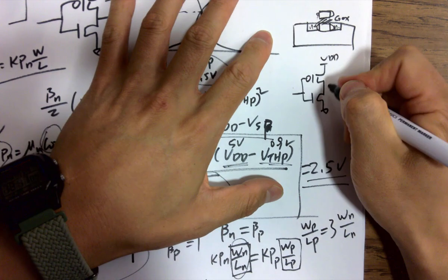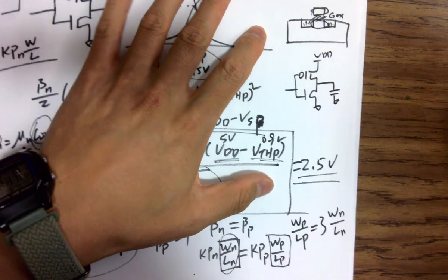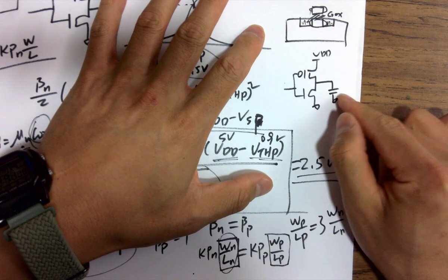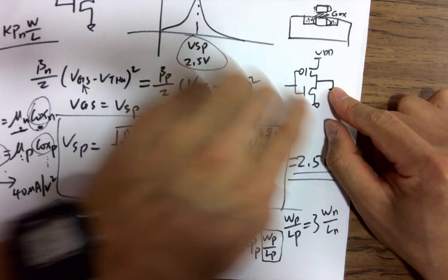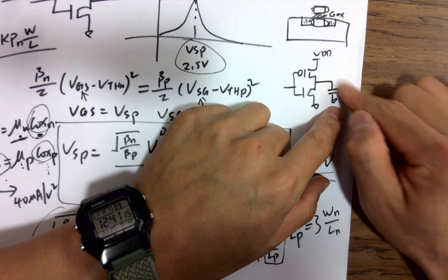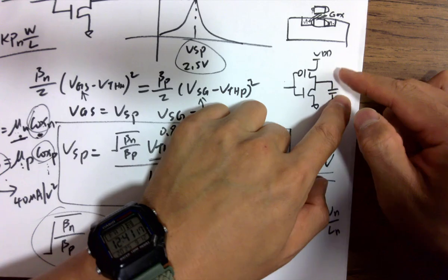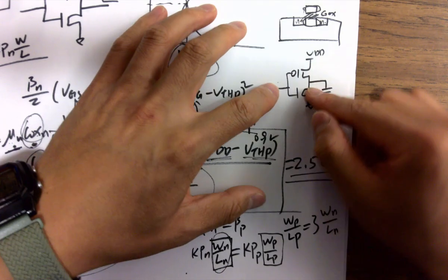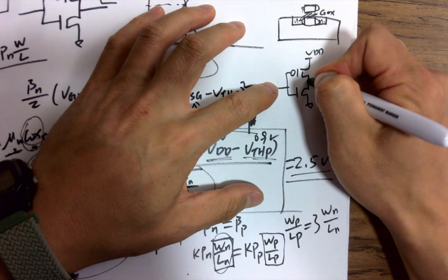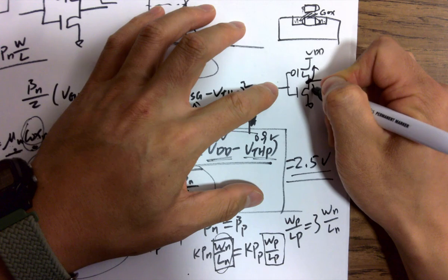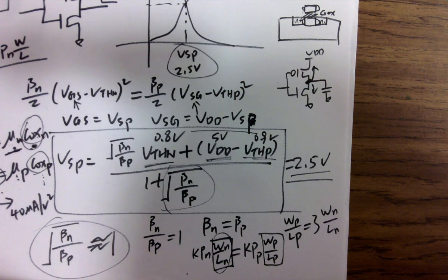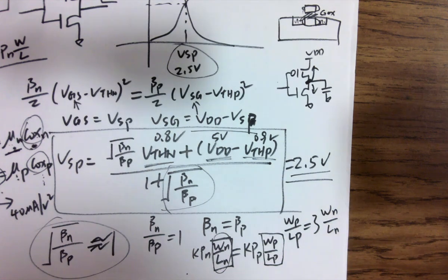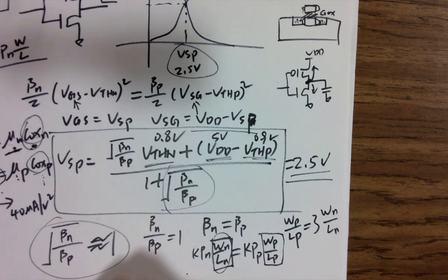So whenever this guy is driving the following circuit, I'm just modeling everything here as a capacitor, but they are just RC circuits, digital circuits. You can eventually model it as a capacitor, charging and discharging the following circuit. So whenever it's doing this, you can imagine this point is actually being either put up or put down by these two transistors. So the strength of the transistor really matters over here. Why is that?